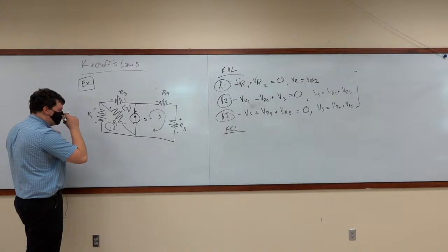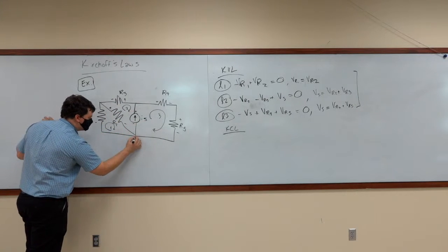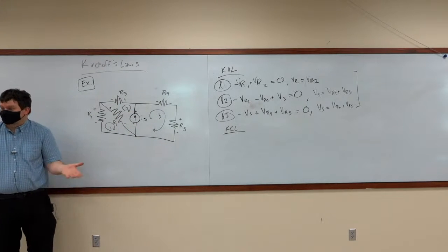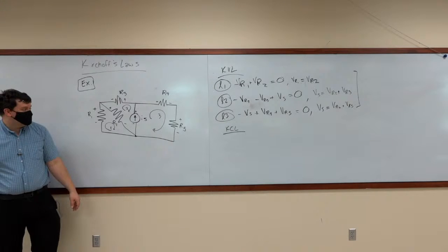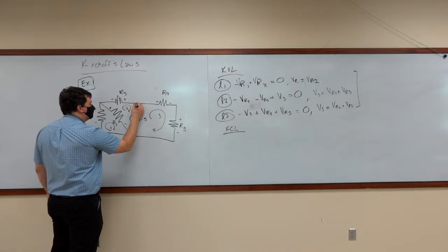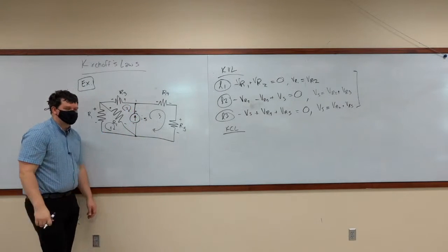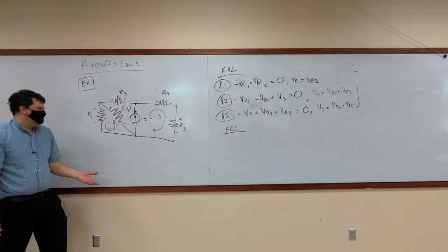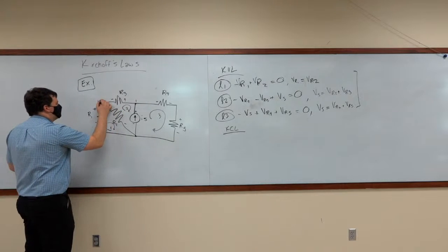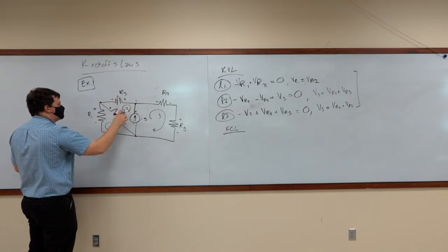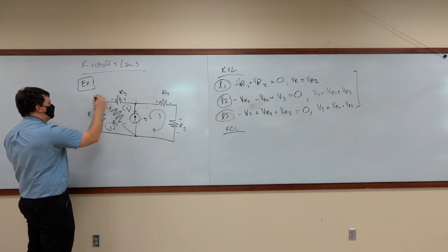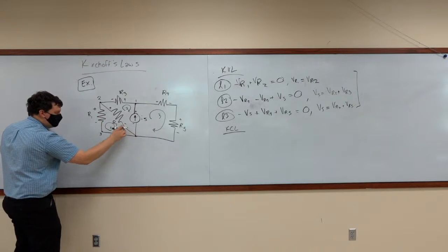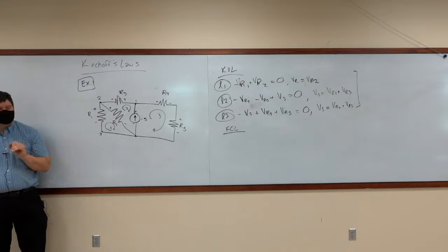What I'm going to do here is, again, I'm going to identify the nodes because I want to show you how I would do it. It doesn't matter which node is number 1. It doesn't. I like to make node 1 the first node after the source voltage, because then node 1 has the highest voltage. But it doesn't really matter otherwise. And then you just start drawing other places. Here, this collection, I'm going to call it node 2. This piece down here is node 3. Node 3. Huh? So which would be 4?